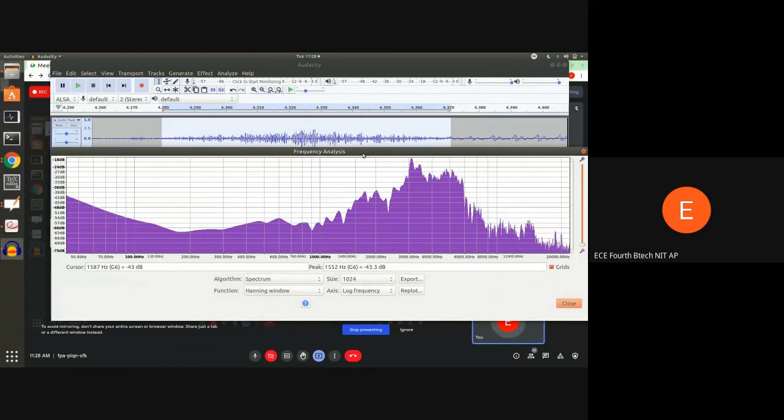Look how the spectrum looks like. You do a Fourier transform and you get your amplitude or magnitude spectrum, and phase spectrum. Here only the magnitude is being plotted. Just look at how it is. You see, it is in the high frequency region. There is a lot of energy in the high frequency region.